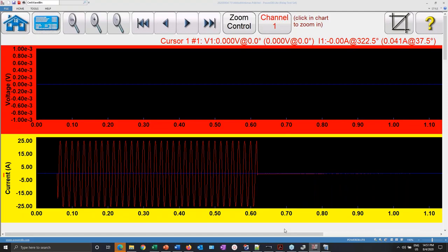So you take the result. I guess I'm describing a process that would be familiar for many, but there is also another use for this, which is doing end-to-end testing using this type of file. You can generate the faults in a more realistic form than the one I have right here, with a DC component, with harmonics, with other elements incorporated. What I did right here was I created a fault, played it into the relay, and took it from the relay and back into the realm of the RTMS.